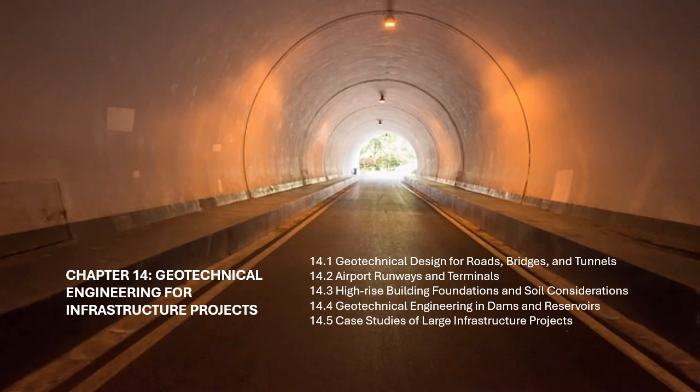Geotechnical considerations. Soil strength, compaction characteristics, and the ability of the dam to resist erosion are all key factors. The core must be designed to be impermeable to prevent seepage, and the outer layers must be stable under both static and dynamic loads, such as those from earthquakes.